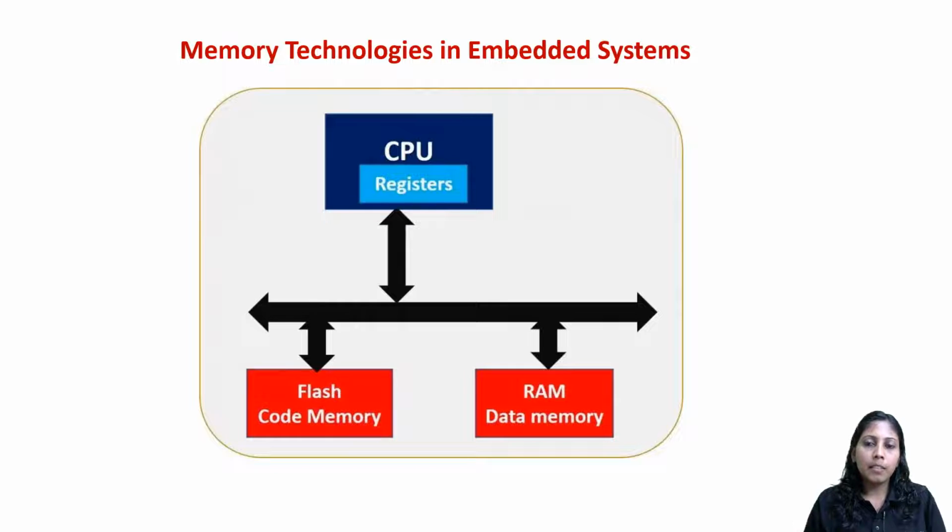If you want to have more data in the CPU registers, the controller should have several registers. In basic controllers, you will see only a limited number of registers. On the other hand, advanced controllers, like the 32-bit ARM controller, have so many registers in which you can store more data. The ARM controller is based on load store architecture, so you can keep everything in the CPU registers and the fetching will be easy. Hence this kind of microcontroller will be faster and able to process data quickly.